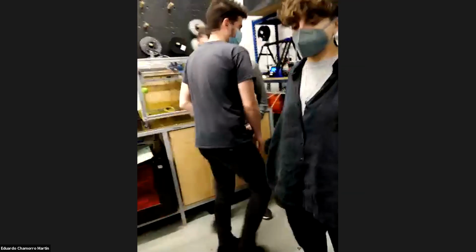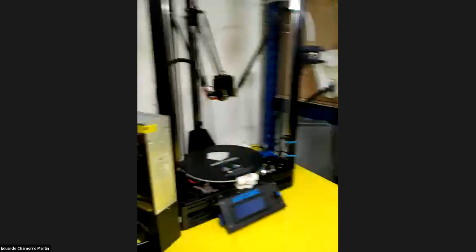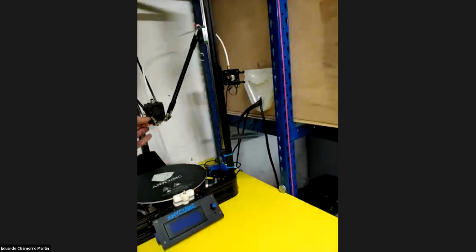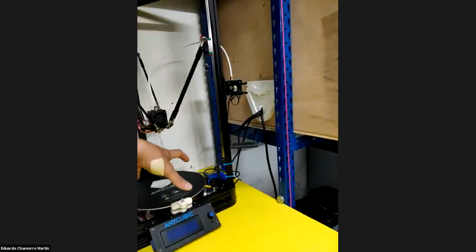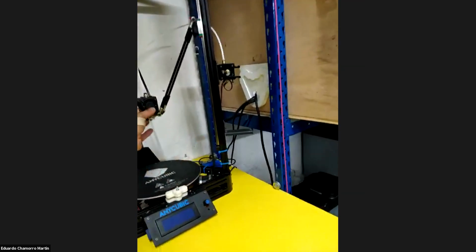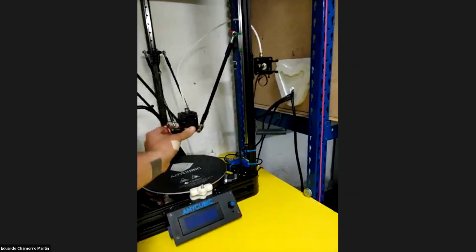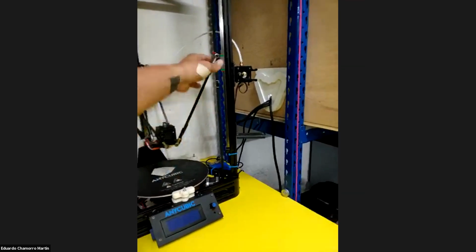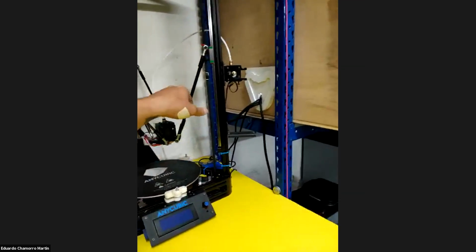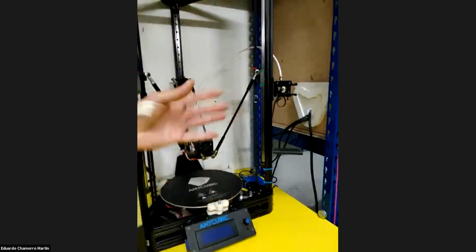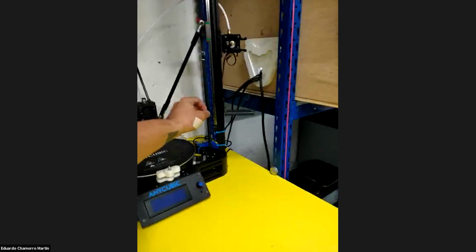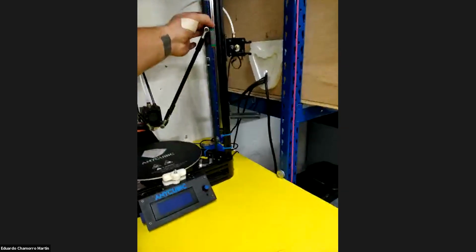So, sorry. For example, these are Delta machines. In a Delta, you have smaller motors for moving the axes, and the 3 motors combine for X, Y, Z at the same time. That means we need to produce smaller movements, but we need to do them faster, because a small movement in this one implies X, Y, Z at the same time. So we need to make faster movements, but accurately, because just a little movement of this guy moves a lot, so we went through again linear rails.